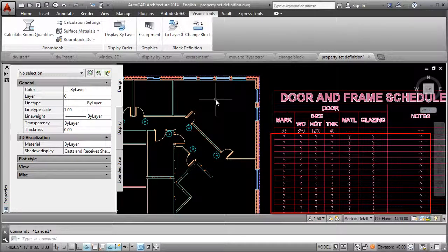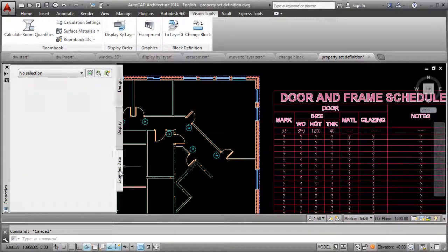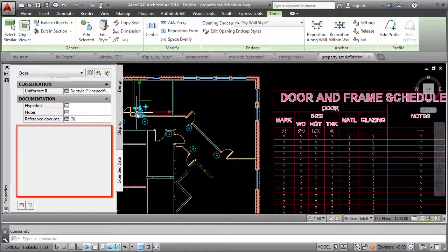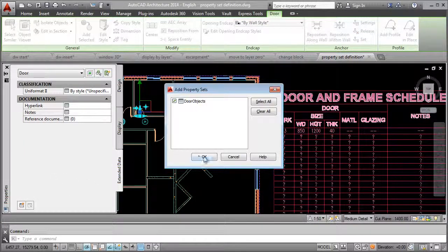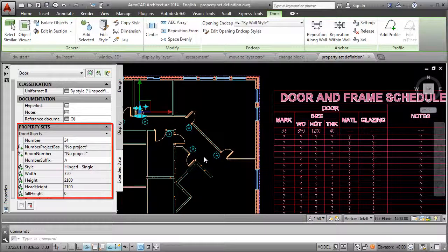Do you have schedule tables that are full of question marks? Do you export drawings to DWF only to discover that the expected properties are not present? To fix the problem, you had to individually attach property set definitions to each object. This can be very time-consuming, especially in large projects. With the automatic attachment of property set definitions, you will not face this problem anymore.